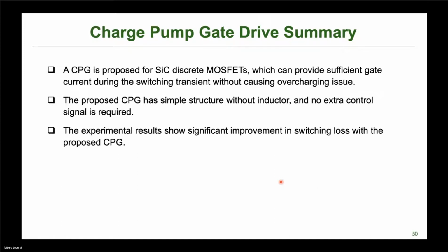There are things such as, sometimes the soft switching only works over a certain load range. And he's worked on some ways to widen that load range, where you can soft switch over a wider range. And the timing is very critical in these very fast switching devices like GaN, such that you are soft switching all the time, but you're also having to make sure you're in that resonance and whatnot.